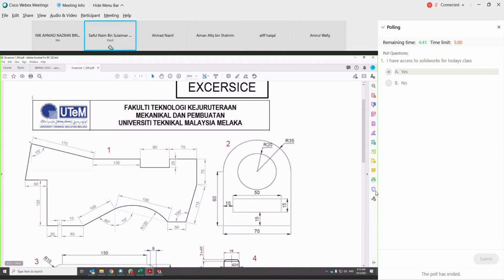Looking at the first part, we have a block consisting of lines and arcs only. There is only one arc. Most of these are lines. And then it is also very important to decide your origin point or 0, 0 point, because when you do sketches, the part must have reference to the 0, 0 point. So for example, you can choose this as the 0, 0 point, or you can also choose this as the 0, 0 point, wherever you feel it is easiest for you to start.